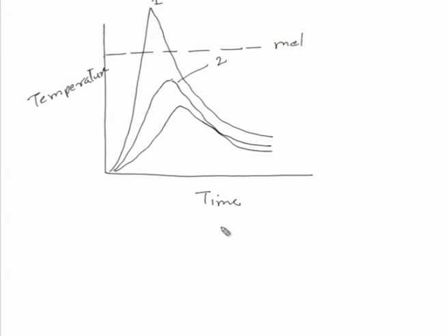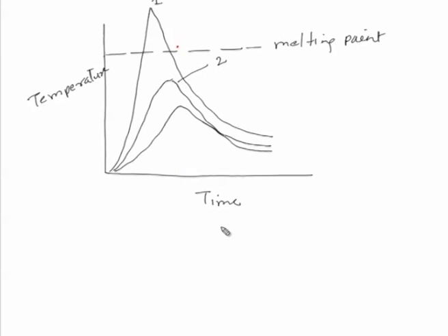So, say this is the melting point temperature of the base material. All the regions which are falling above this temperature will be forming the weld metal, and melting will be taking place, and after solidification that will result in the weld metal.